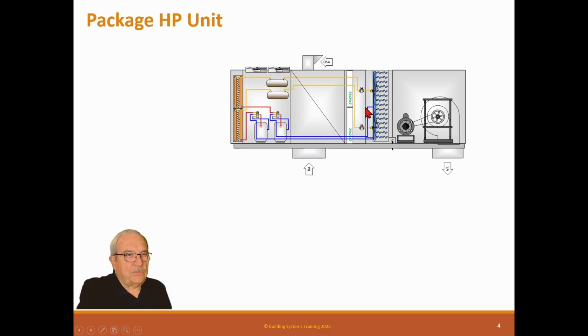Now, if you take S1, it'll explain all the refrigerant of a heat pump circuit and what's in it, what's not, and how it exactly works. It's over there in S1 to do that. So this has, of course, the air comes from the supply fan down the space, comes back in, goes through the filters, goes through the evaporator coils and back, and that's the air circuit.